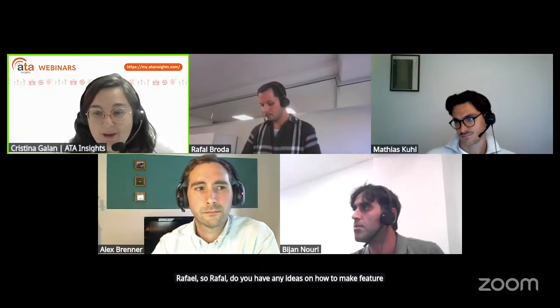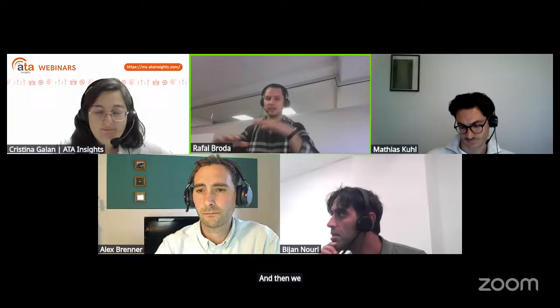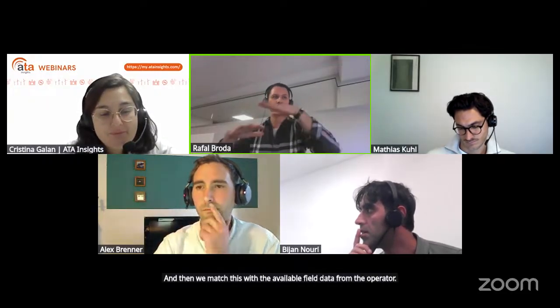So next question, thank you for that, Bijan, goes to Rafal. So Rafal, do you have any ideas on how to make feature identification better? So, yes, we have seen that roughly 60% of features are detected and identified correctly, and have a gap of basically 25% of features which we are losing to identification. And there are two possibilities. First one would be to optimize the flight path, because right now what we are doing is we fly with the drone, record a video, and basically create a point cloud of the field. And then we match this with the available field data from the operator. And by optimizing the flight path, we could have more significant features like edges from the field and so on, which would make the matching better and also the identification better. This is the first case.